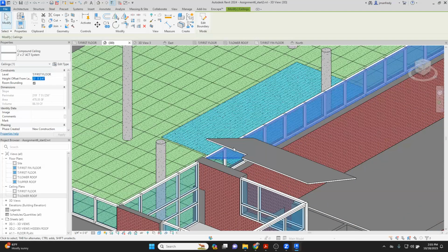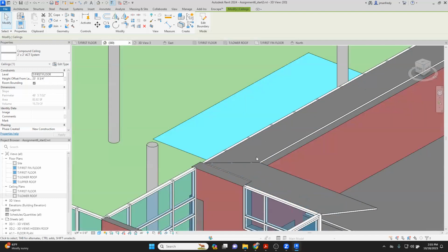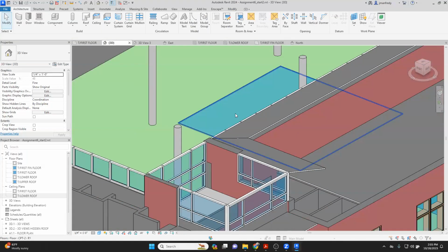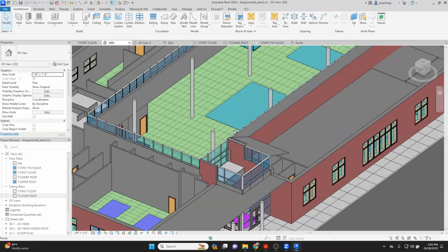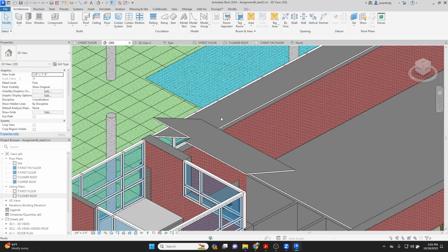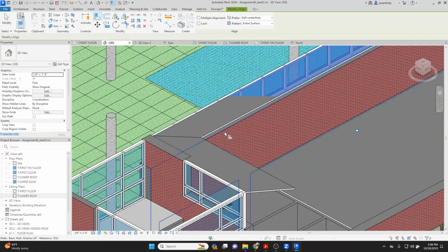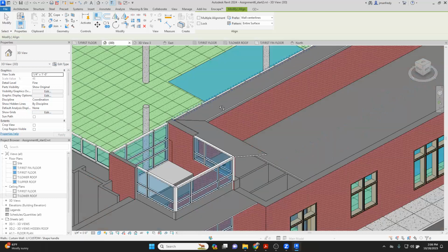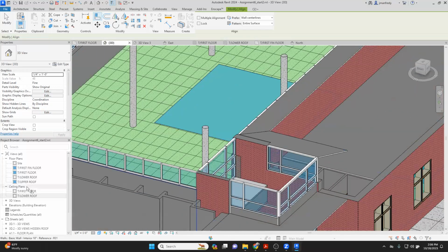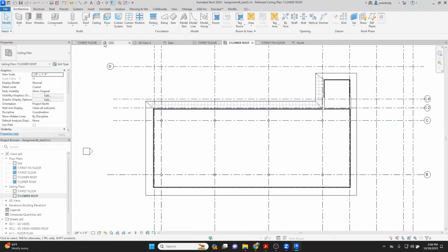And then I copy that to this one. From the first floor up to 23 foot 8 3/4 in this case. You see they connect together. Another quick way of doing it in Revit is simply just align the top of this to the top of that. AL is align. Hover here. It grabs the top of that ceiling. Grab the top of this ceiling. Now they're lined up. It's another quick way of drawing that. So you'll trace the edge of the ceiling all the way around, and then you'll quickly make the one on the inside.